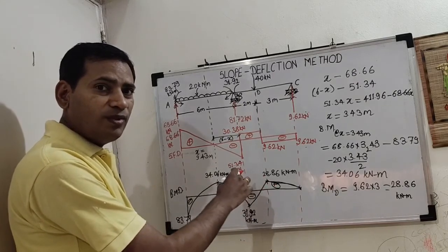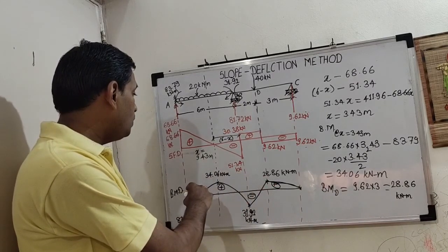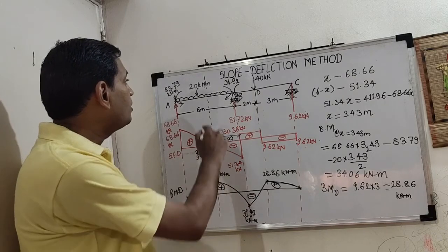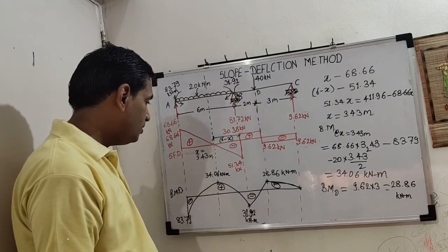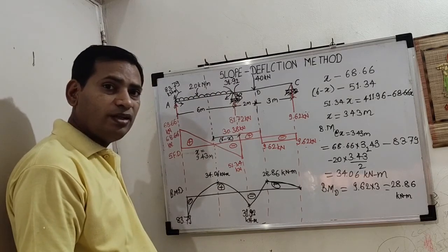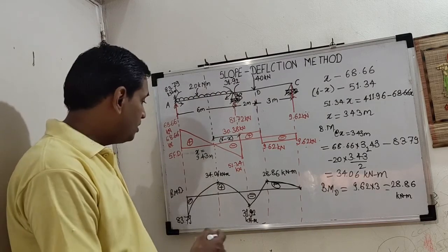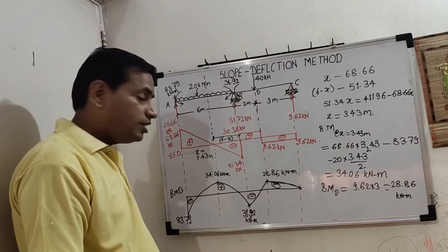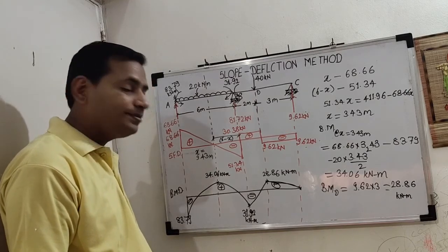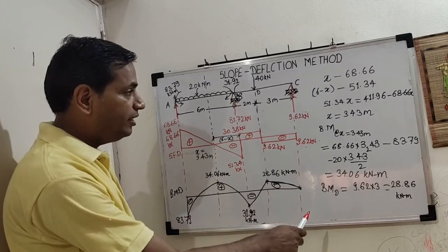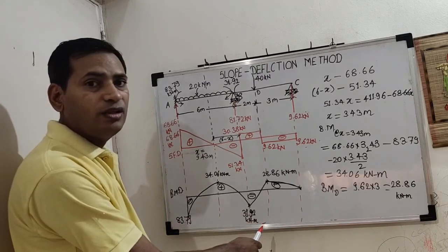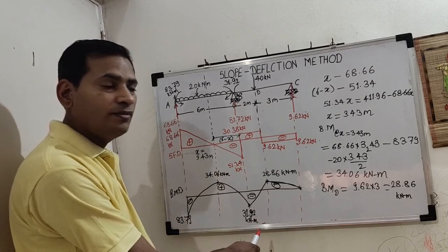Over that fixed end moments, they overlap bending moment diagram because of external load. Do not make this practice, because that is not going to get any concepts clear in the next subjects like structural design. Okay, so BMD on tension side is important, lengthy, but this is the correct way for the approach.